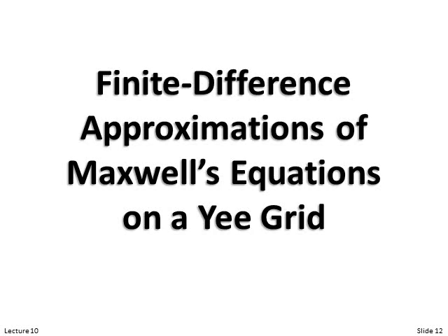Now here's probably the most important part of this lecture, and now we're going to approximate our finite differences, but we're going to locate the field components consistent with Yee's grid.